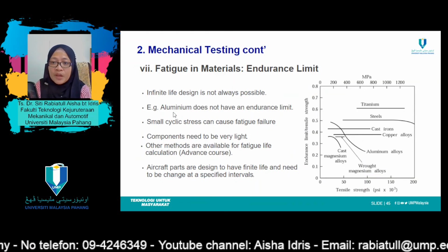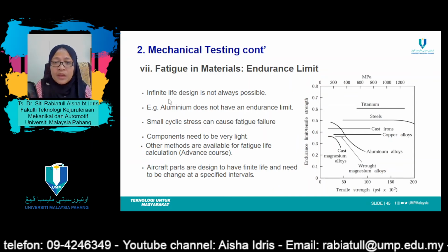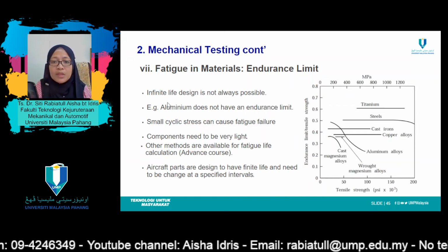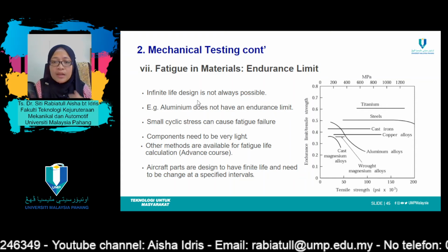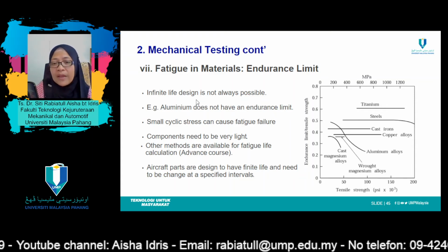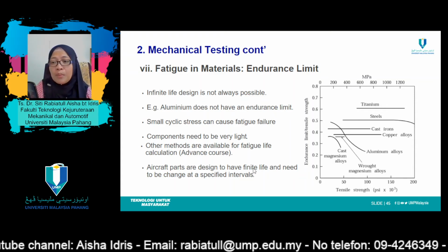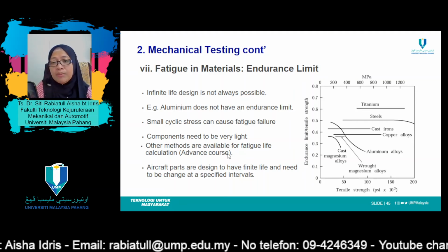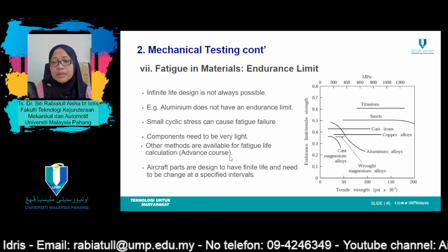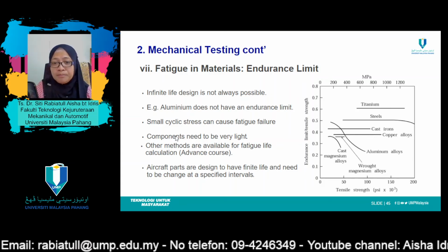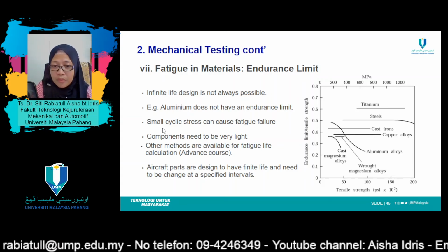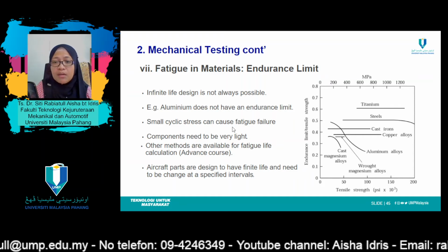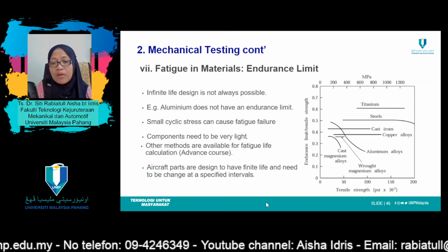And the endurance limit actually refers to infinite life design. This infinite life design is not always possible for every type of material. For example, aluminum just now does not have an endurance limit, and therefore small cyclic stress can cause fatigue failure for these types of materials.